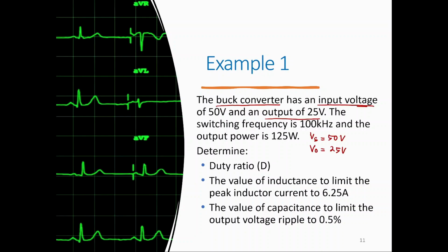If the type of converter is not given in the question, let's say there is no buck mentioned, in order to identify which equation is suitable for that particular converter, look at the information of Vs and V out. If it's a step down, which is your V out is smaller than your Vs, this is buck converter.